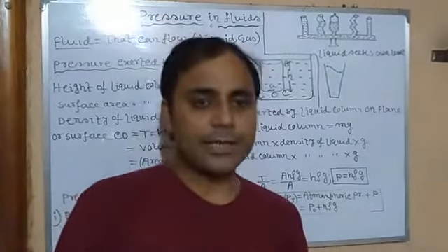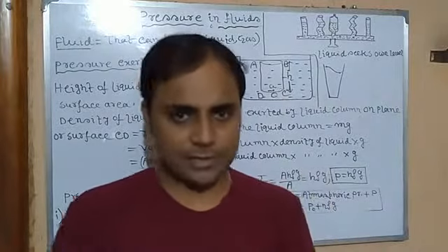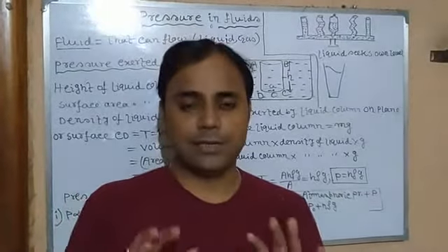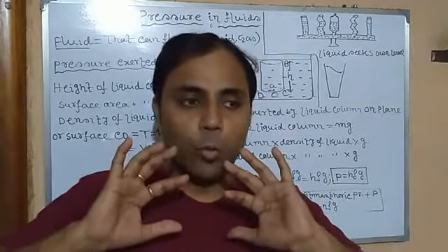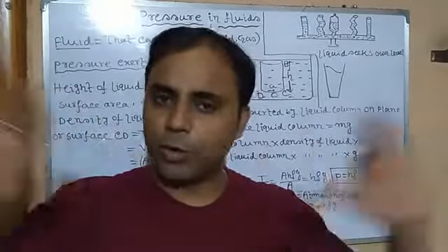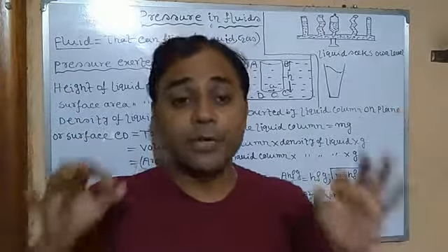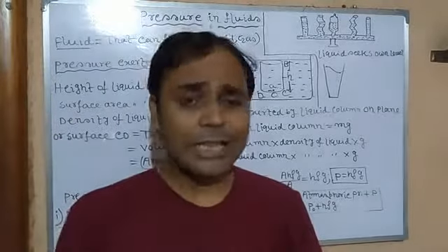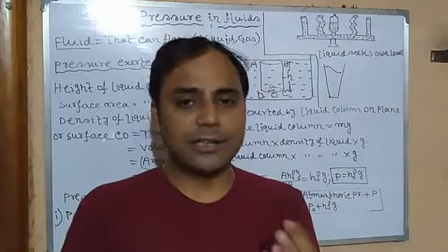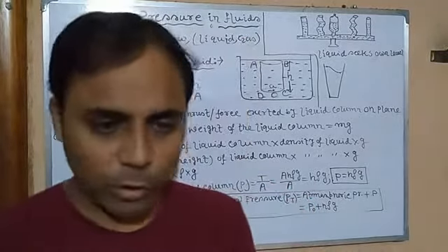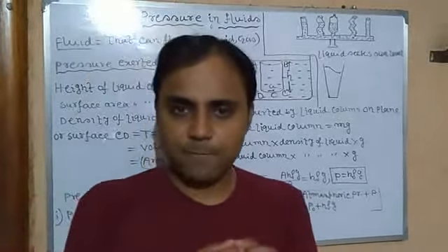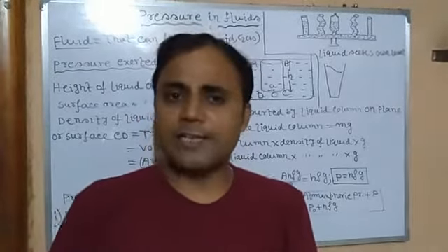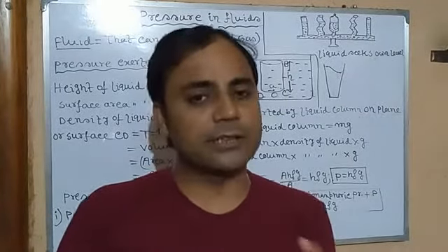But unlike solids, in the case of fluids, that is liquid and gas, they exert pressure at the bottom as well as on the boundary wall, or the wall of the container in which they are kept, due to their tendency of flowing. Clear? Now since liquid has greater weight than gases, since the intermolecular space is less and the compressibility is less than that of gas, the pressure exerted by liquid is much greater than that of gas.